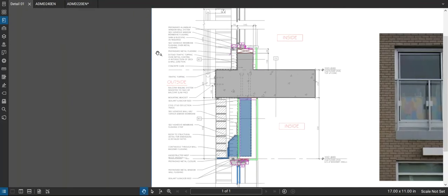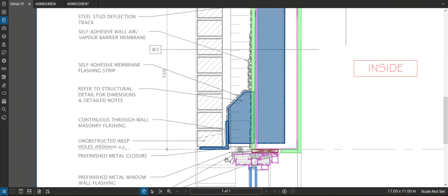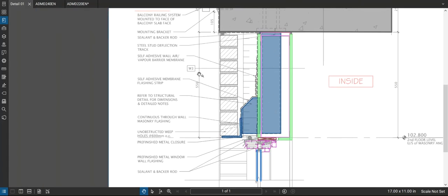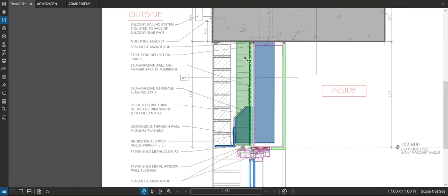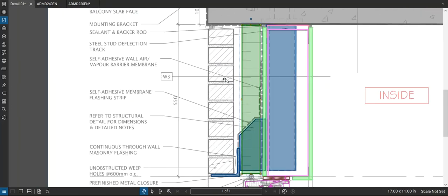Okay, so next, let's take a look at the insulation of this building. This is a fully outside insulated approach, okay? So there in the green is the outside insulation. Again, there's not very much there. I didn't check the wall tag to see what that is, but it looks like maybe 75 millimeters. My brick is 90 deep, so yeah, it's about 75, so 3 inches, which was normal 10 years ago or so.